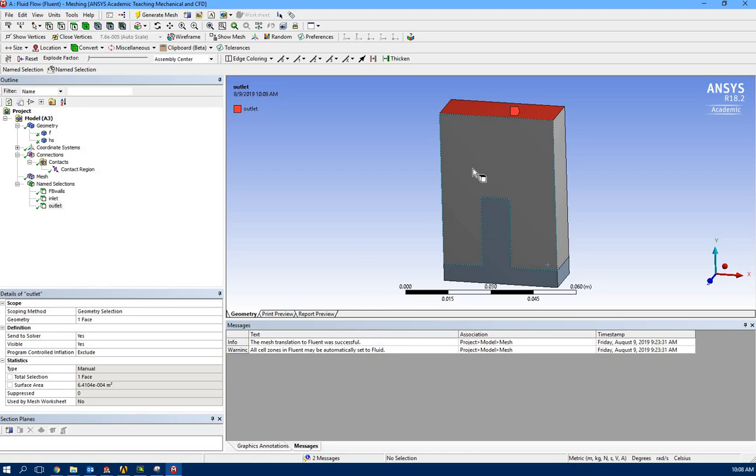So if you start simulating, we expect this heat sink at 35 degrees to gradually cool down and heat up the air around it, and the air after heating up is going to have less density and get lighter, and it's going to rise around this fin upward. And with passing time, we expect to have lower temperature inside this fin till reaching room temperature. Okay.